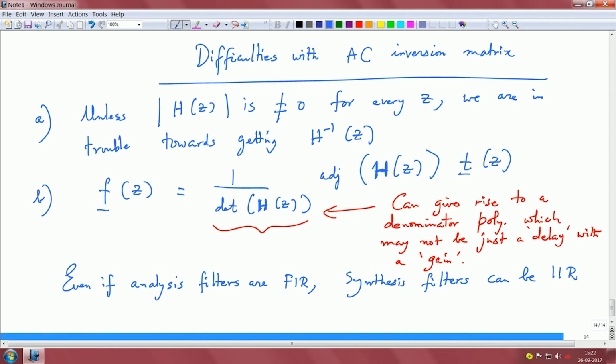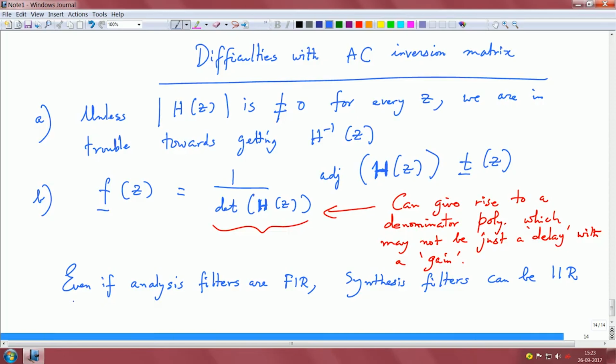Round off noise, stability, and a lot of these issues are there, right, and when you do quantization, even a small shift in the pole position, right, can alter your response significantly, or you can drive the system to instability, right. These are very, very important considerations. So, I think as an offshoot of this, I mentioned to you that this implies that stability can be a problem.